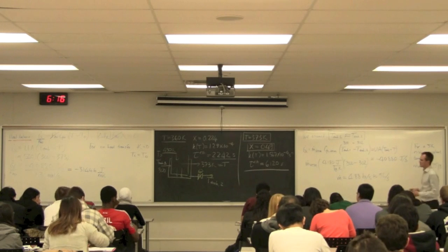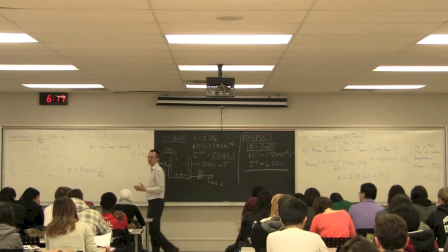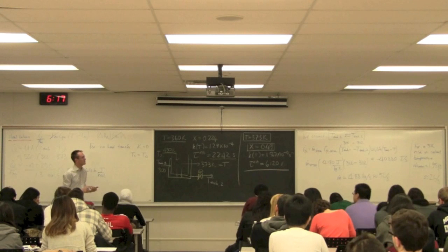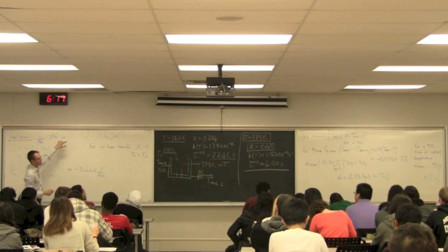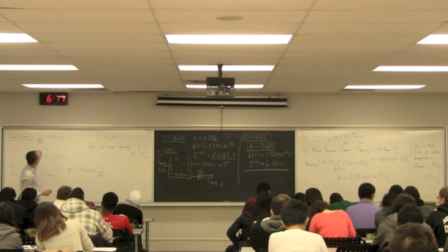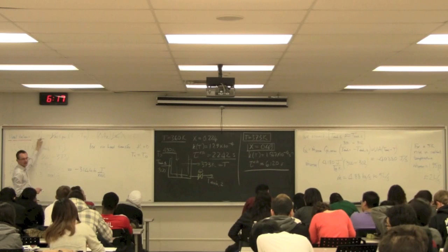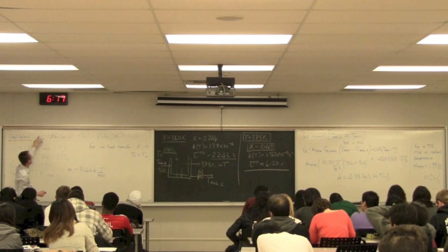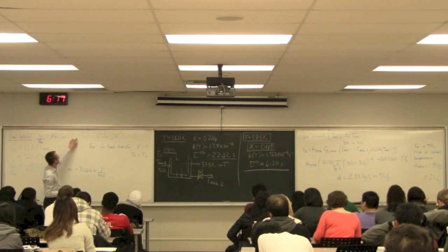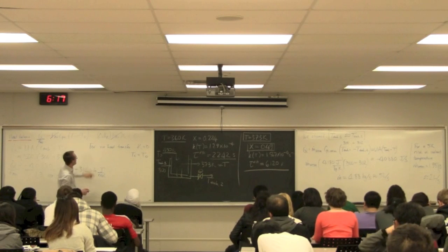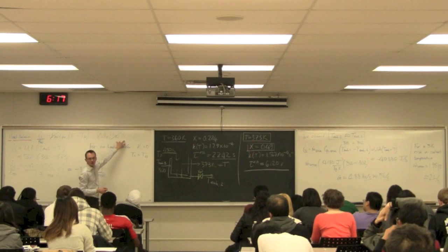So the point here from this class this evening is when we're looking at problems, not just to solve them and get to the final answer. We got our temperature, we got our conversion, but actually interpret these individual terms in these equations. Play around with it, see what happens if you set one equal to 0 under a fairly realistic case where someone closes the valve, for example, and Q0 goes away. Or what happens to conversion if T is equal to T0? Or what happens to my process when conversion is 0?